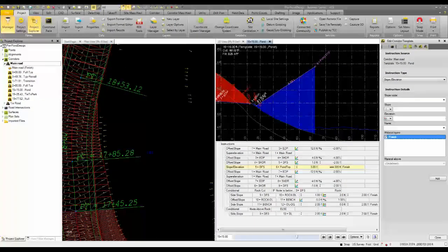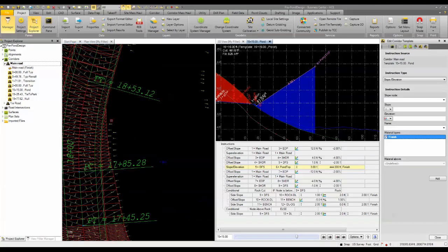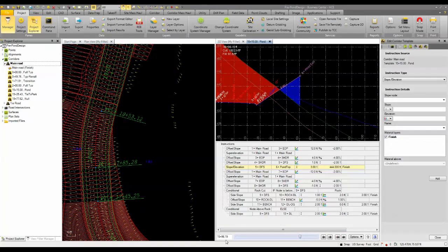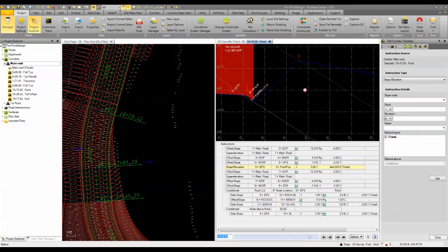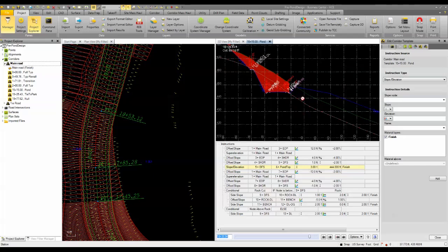You'll notice up in this area though it stops, because at a positive 3-to-1 we're actually below the original ground. So if I move my cursor up to this location here, you can see that that 0.6 is below basically the original ground. So 444 doesn't exist here. It's actually got to be continued down here. We're actually below the original ground.